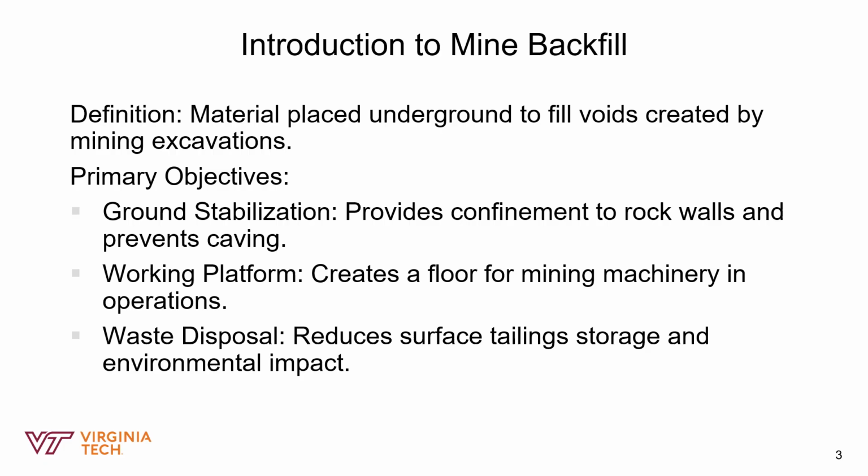So mines produce massive amounts of waste tailings. So instead of storing them in tailings dams on the surface, which can fail or even leak into surrounding water bodies, we use this material as structural support underground. So in that case, we don't have to waste money to construct tailings dams. We don't have to worry about the tailings seeping into nearby groundwater bodies. And so we are basically reusing the waste material as a support system underground.